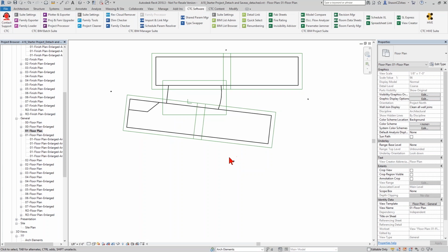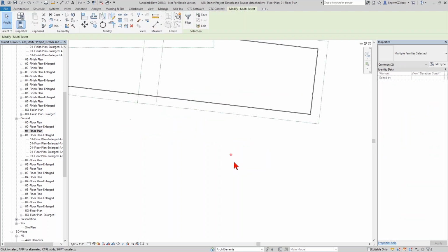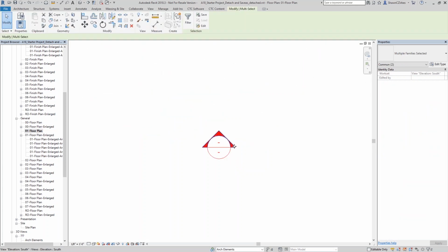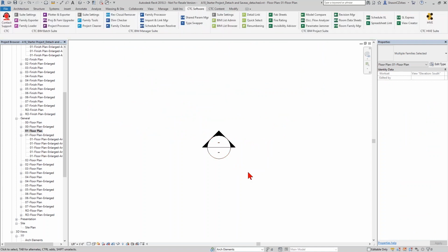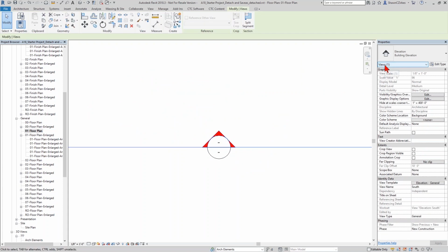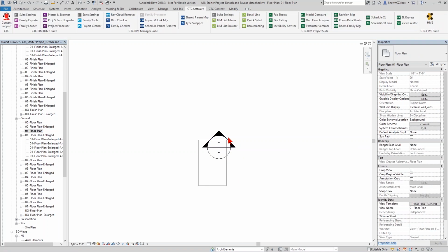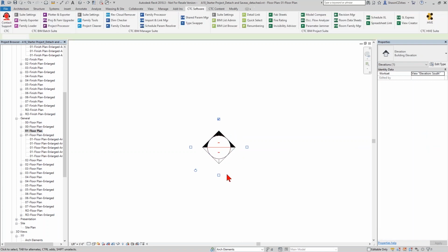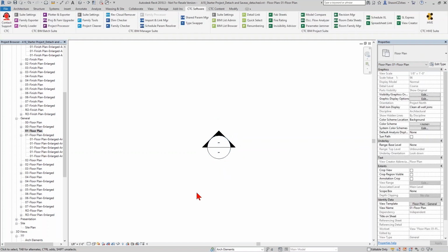What will happen also, by the way, with those graphic tags is it doesn't show them on top of each other, because the elevation tag itself will only show for the phase with which it is associated. There's only one tag right here. If I highlight just this, there's just the one view that's available and visible in new construction. And there's only one base tag down here, again, that's also visible in new construction, because the existing tag now only exists in the existing phase.